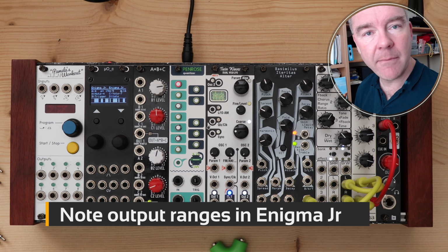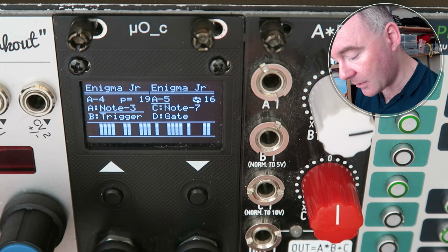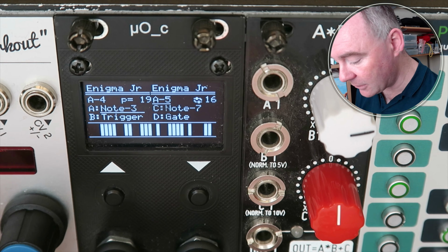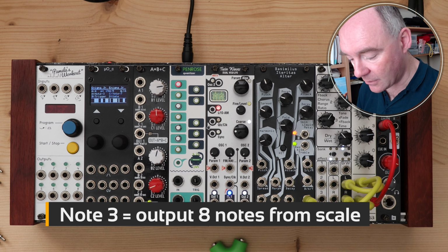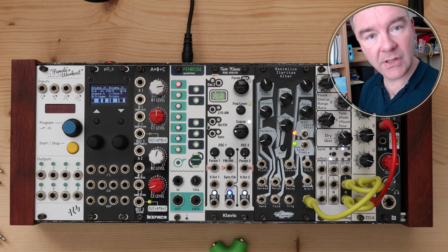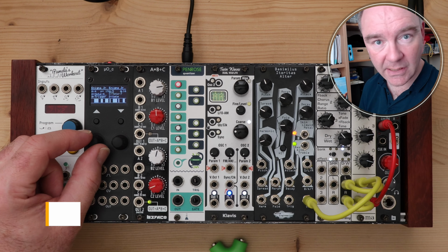That talks about how many bits of information are used to create the value that will be output. The values that are available to you here for this parameter are 3, 4, 5, 6, 7, and you have mod and expression. And of course, it can also be a gate or a trigger. Let's look at what they mean. Note 3 means use 3 bits of the value of the register to create a value. 3 bits corresponds to a range of 0 to 7. So that means the notes that will be generated are just 8 notes of the selected scale. If I set this to note 4, I'll quantize it to 4 bits of information, so 16 notes.